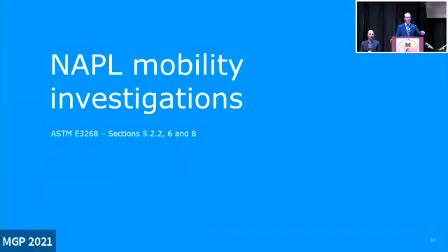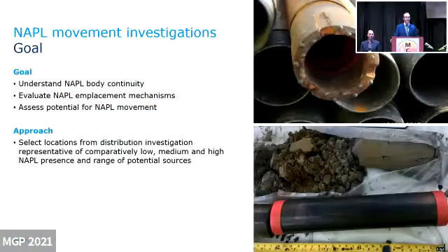I guess a word about NAPL mobility investigations. Once you understand where NAPL is present in the sediment body, then you really want to start understanding the continuity of NAPL in the sediment and how it might migrate out of the sediment, discussing a lot of things that Mike had presented on. And during this phase, you're typically going to want to collect a lined core and send it off to the